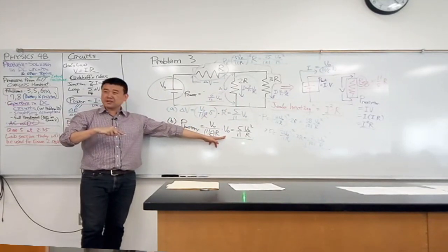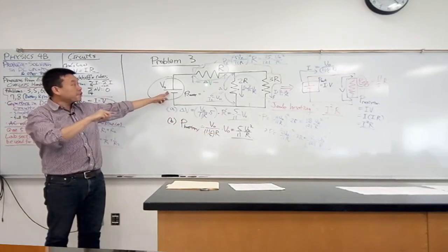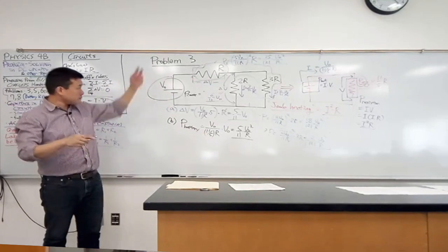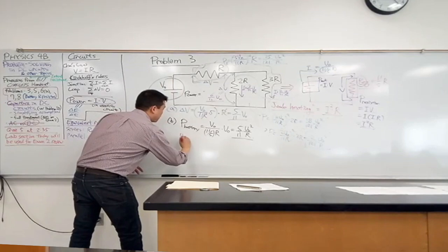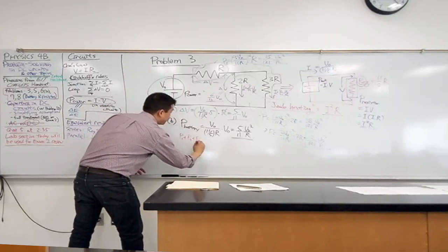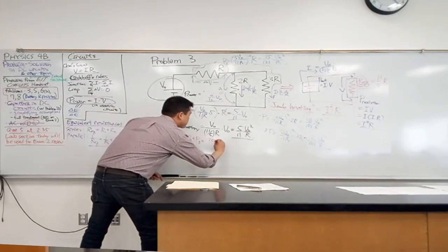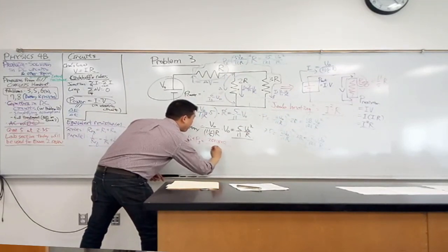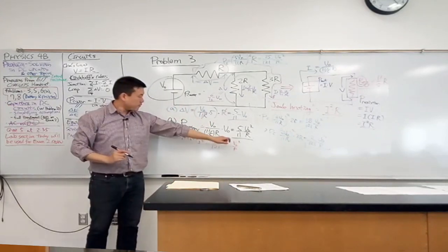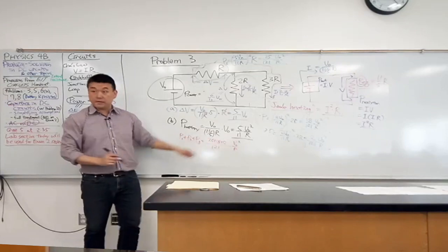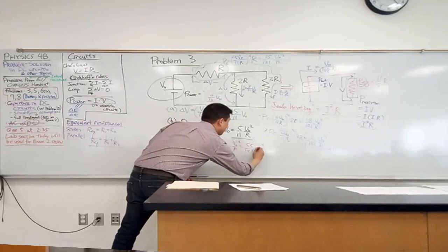Do people agree without actually doing the calculation? Yeah. That would come from energy conservation. Whatever energy comes out over here comes out through the resistors here. So let's add them up and see. We are calculating the total power, P1 plus P2 plus P3. We are saying 25 plus 18 plus 12, divided by 121, V naught squared over R. Add this together, 30, 25, so 55. So this is 55 over 121 V naught squared over R.